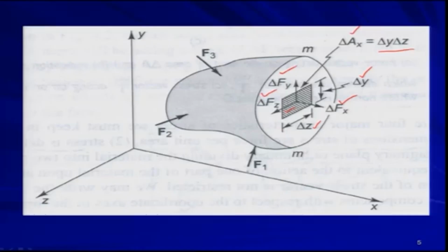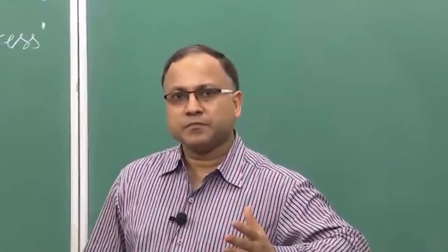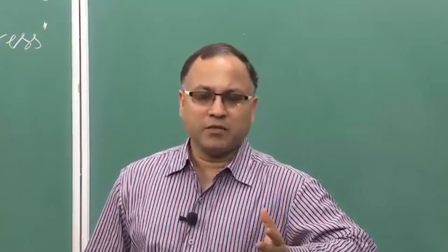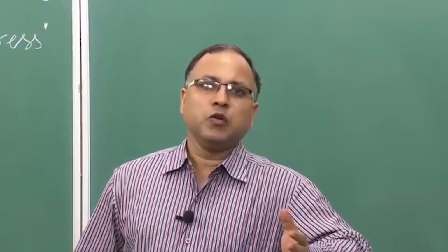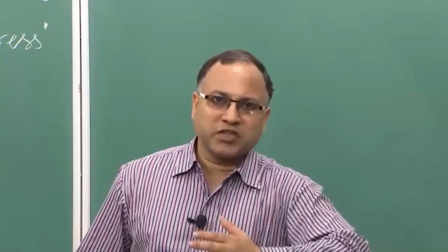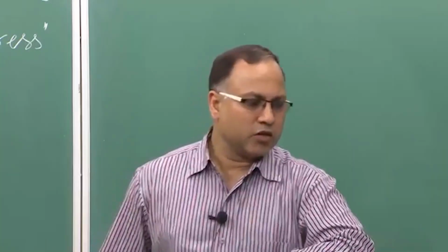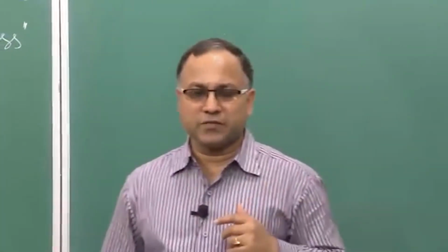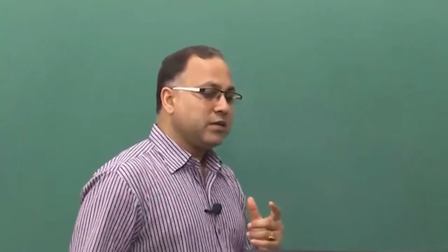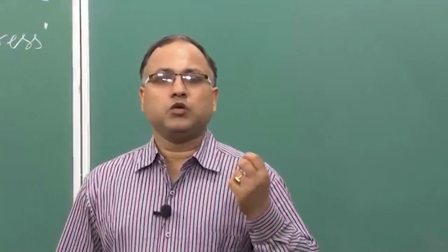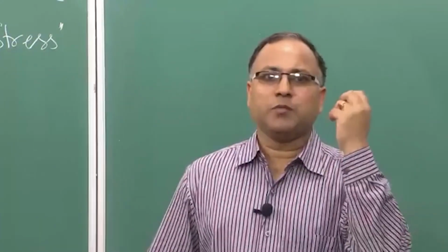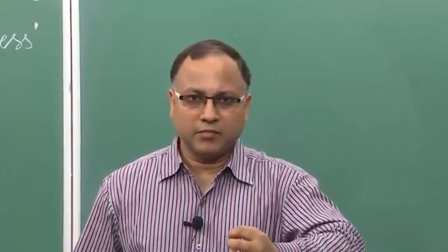Now, this delta Fx, if you look at, this face is nothing but the positive x face as per our definition, because the direction normal on this face will be towards the positive x direction. So, therefore, this face is nothing but the positive x face. Once it is the positive x face, this delta Fx will be acting as the normal, or perpendicular, to the plane.